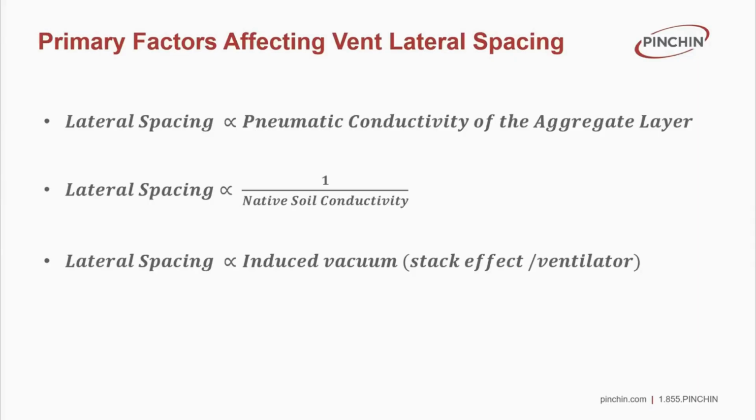And lateral spacing is directly proportional to the induced vacuum. Through the vent riser, whether we're using stack effect or a ventilator turbine, we are essentially inducing a vacuum in the subslab environment. The higher the vacuum we are able to induce, the farther away we can space out these laterals.